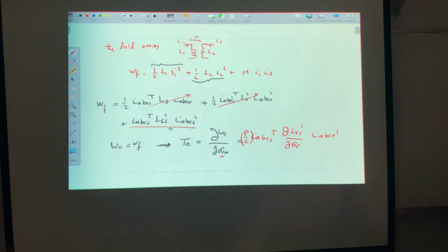Now see, the mathematical model itself is time varying. And until now, unfortunately, we don't have any tool to deal with a time varying differential equation. The second thing, the torque expression will be what? 20 terms, maybe, and you don't know where you should modify. For example, in the DC machine, it was very straightforward. If I need to control the torque, I need to control the armature current. Here, if I need to control the torque, which current do I need to control? How to control it? Stator or rotor? So this one is very difficult to deal with.